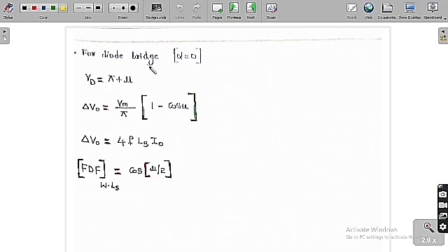And if you want to find the fundamental displacement factor, without source inductance it is cos alpha, and with source inductance it is cos of alpha plus mu by 2. As alpha is equal to 0, without source inductance we get 1, whereas with source inductance we get cos of mu by 2. So these are some of the important special conditions of this 2-pulse converter.